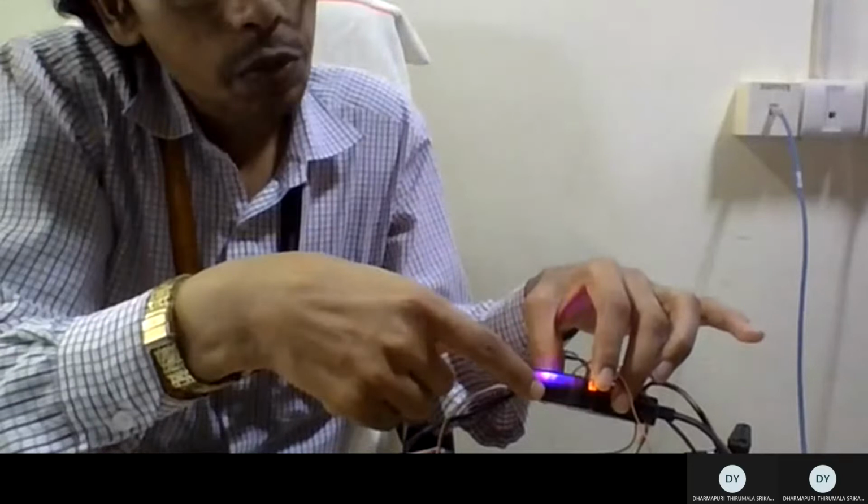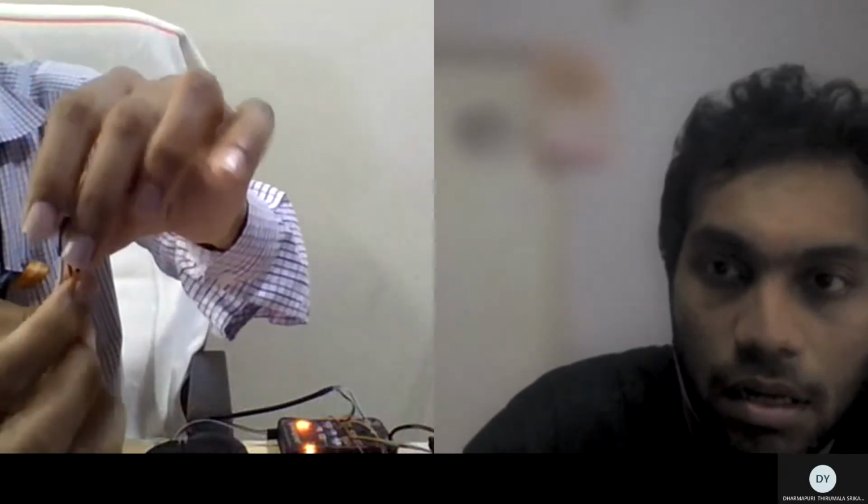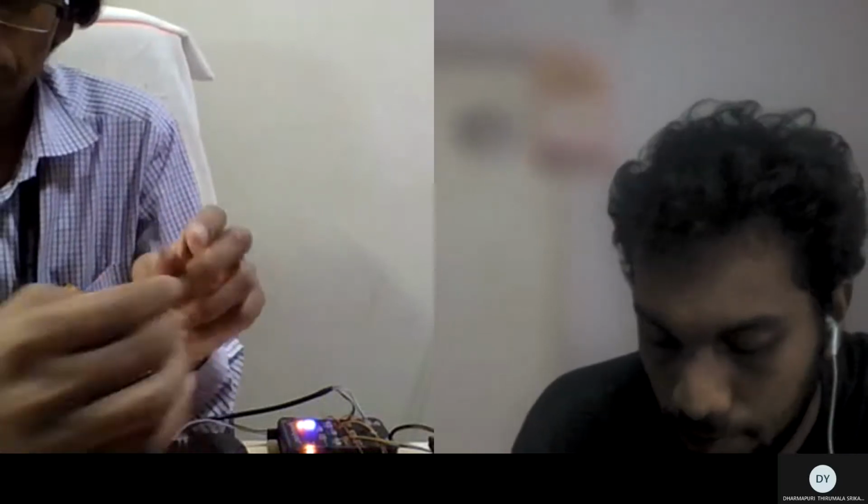Okay, so on the output side, when you are taking output, you have to connect this channel with the ESC. You have a PWM signal, and this has 3 pins, or you can say 3 wires. See this color: white, red and yellow. The white wire gives the PWM signal coming from the flight controller to the speed controller, and the other 2 give the supply.